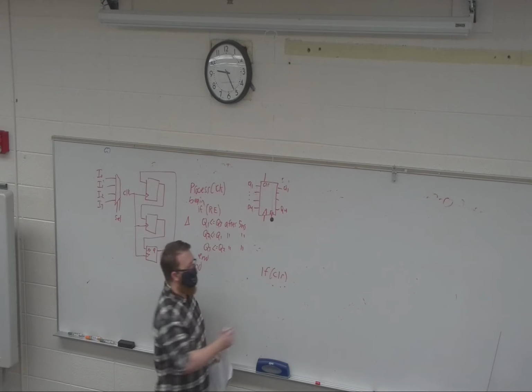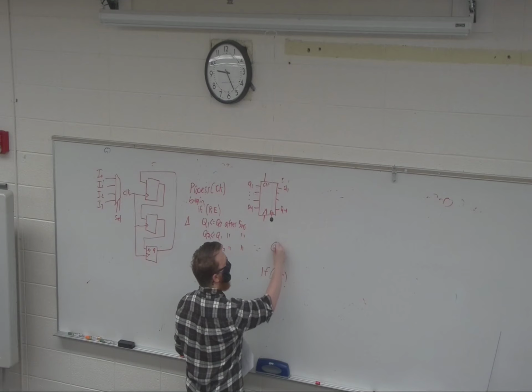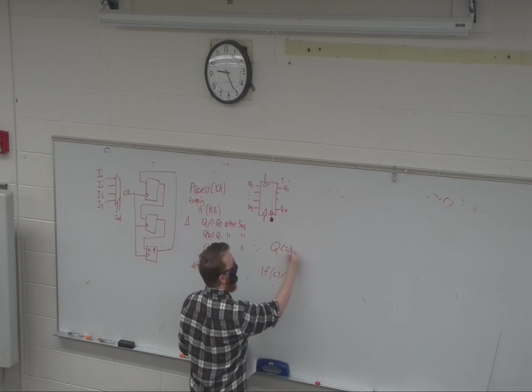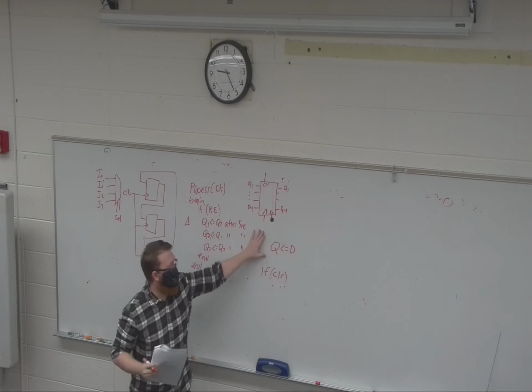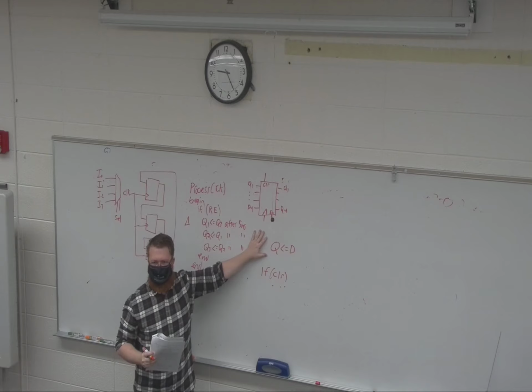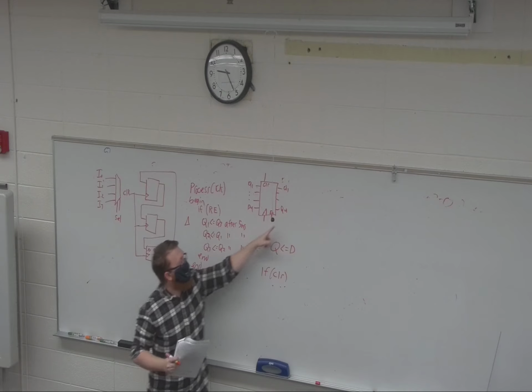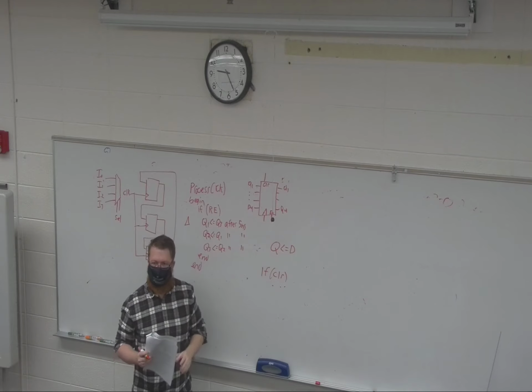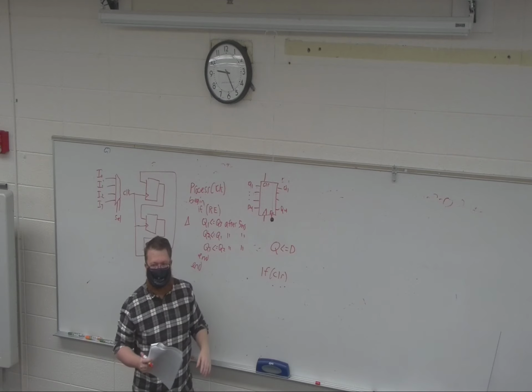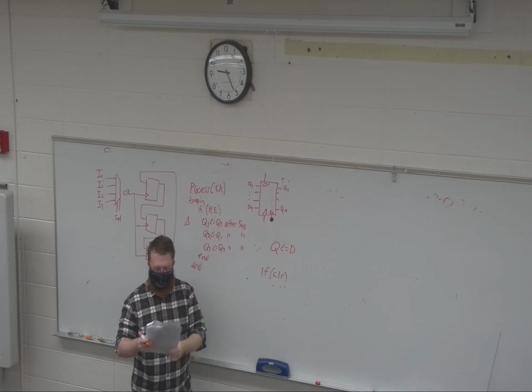And if you remember, with bit vectors, I can really just write that, as long as these are all defined as 4-bit bit vectors. That will assign all 4 Qs to all 4 Ds in order. And then you're done. You have a nice little block of memory.